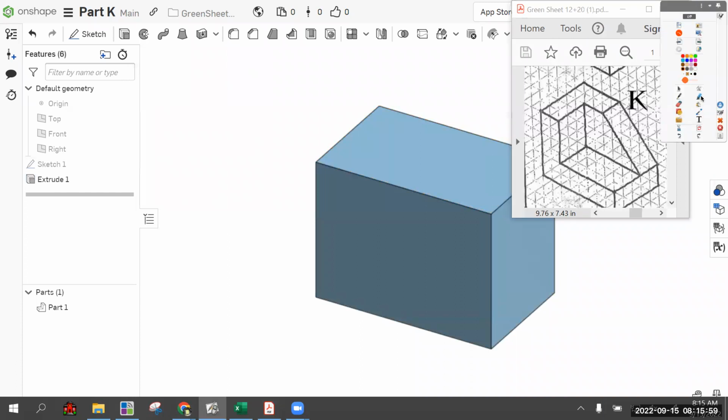And let's cut away what we don't want, which in this case is, let's make this rectangle that is 3 deep and 6 wide. We're going to make that sketch, that rectangle on the top here, and then cut extrude down however far. Okay, so we're making a rectangle that's 3 by 6, and then we're on the top face, which will be up here, and then cut extrude down a height of 4.